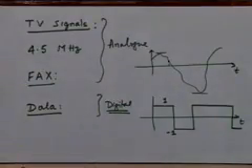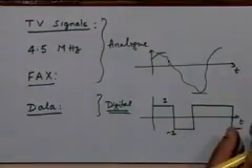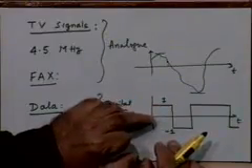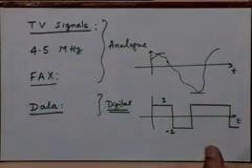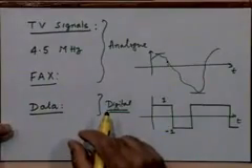So if the signal can only take a binary set of values, or in more general terms a discrete set of values, whereas in the analog case it's a continuous set of values, any real number between one lower limit and one upper limit. But in this case it could be 2, it could be 4, it could be 8, but it will be a set of discrete values. The binary case is an example where it could be 4-ary, it could be 8-ary, right? It could have 8 levels or 16 levels or 256 levels. The moment you have that, it becomes a digital signal, right? So that is one essential difference between these three previous sources of information that I talked about and the data signals that we typically tend to use.